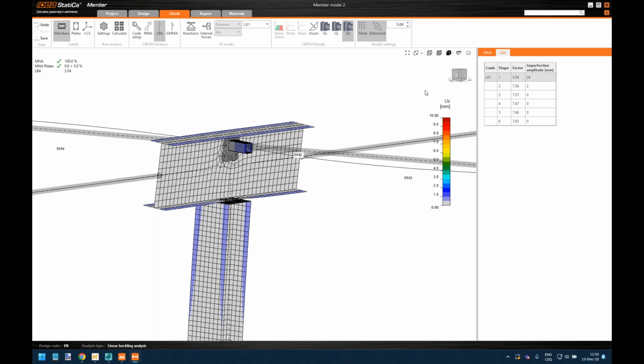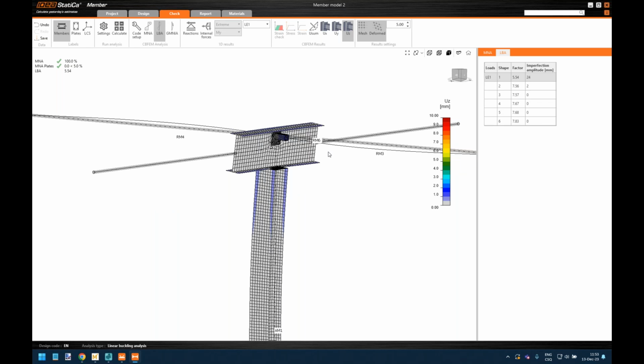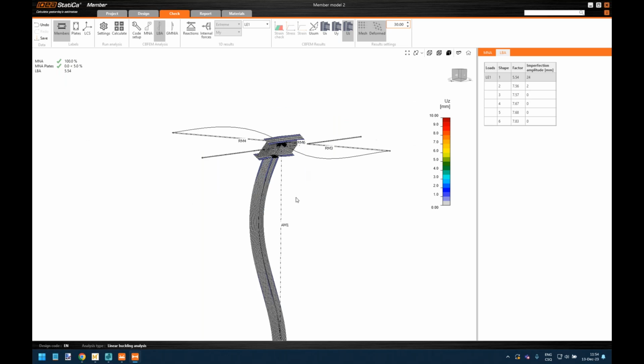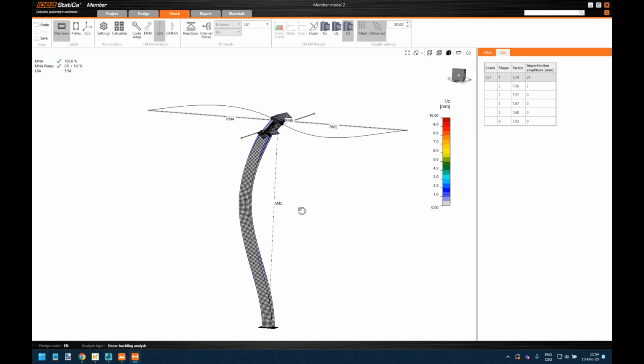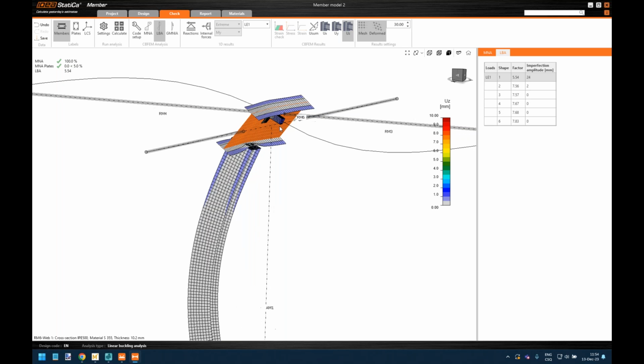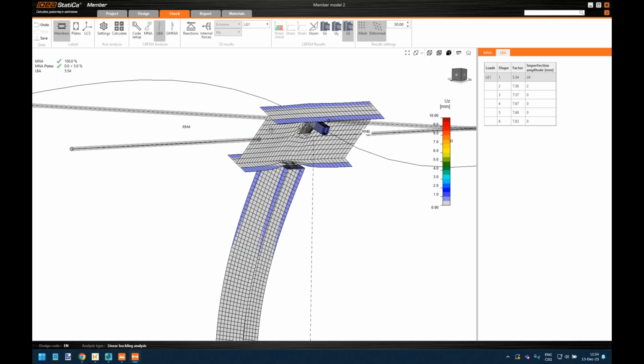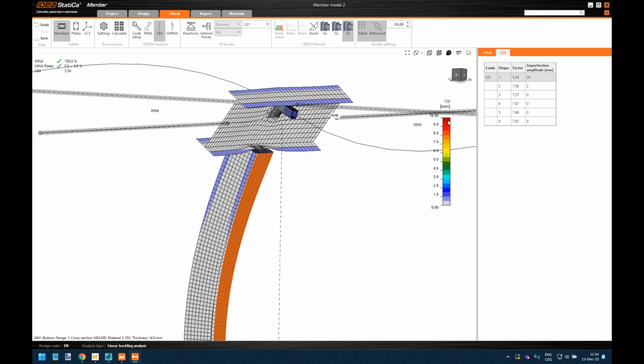And already here with the linear buckling analysis, we can see that the first shape, if you remember, looked very different. It now looks more or less corresponding to the static scheme we would choose: fixed support here, pinned here, there is some bending of the column, and this detail works nicely together, the beam and the column. Also, the factor, instead of 1.3, is 5.5, which is quite high and quite safe.